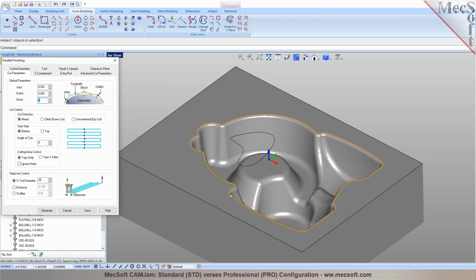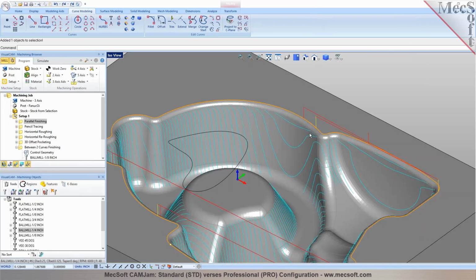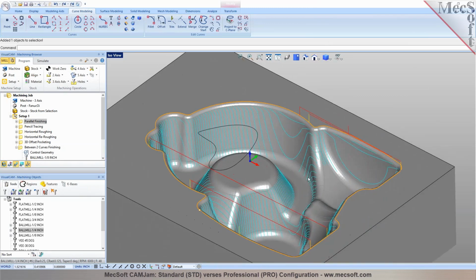You can go past the cutter radius. So for example, if this is a quarter-inch tool, I can't go past an 1/8 inch, but I can say I want to overcut it by 50 thousandths. So it'll uniformly offset it in 3D and overcut it by 50 thousandths. So you can see part of the toolpaths are beneath the surface.